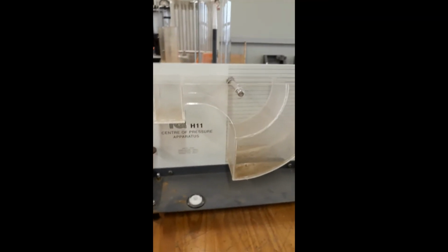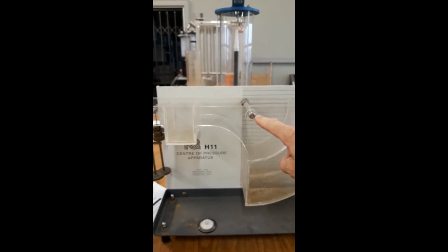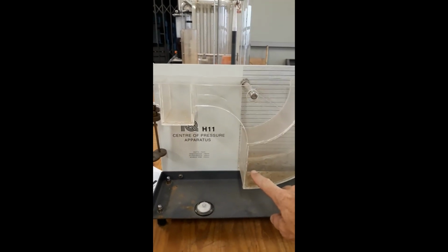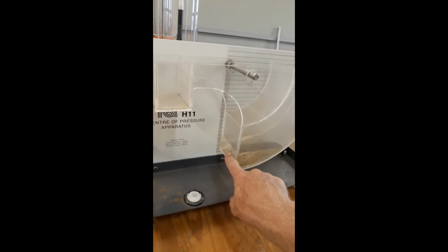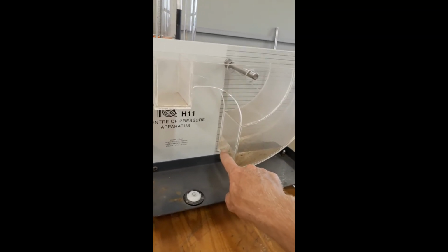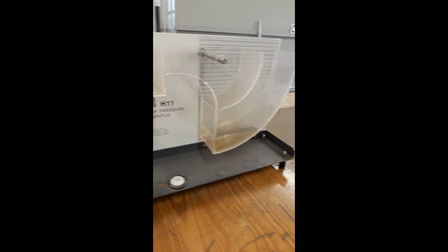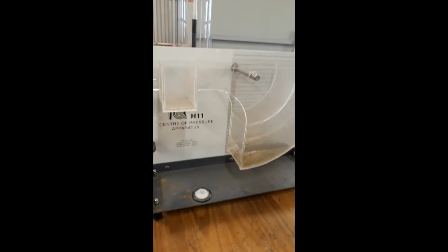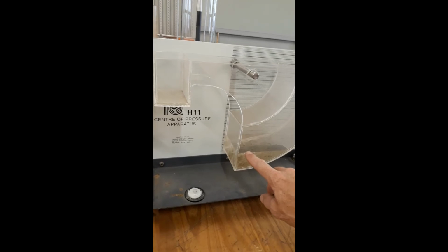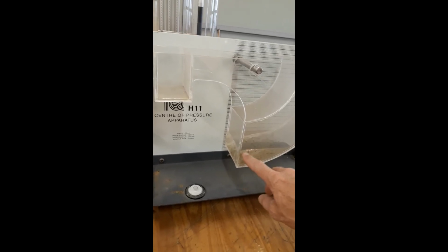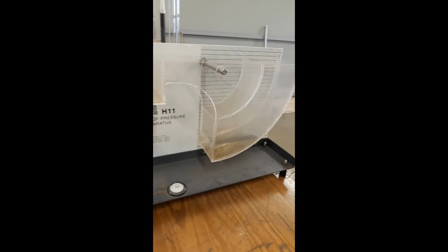In the lab, the raw data we're going to capture is depth 1, from the pivot point to the water line, and depth 2, from the water line to the centroid of the wetted surface. From the centroid of the wetted surface to the COP is a small calculation that you need to do. So you will only receive depth 1 and depth 2. The rest the student needs to calculate.